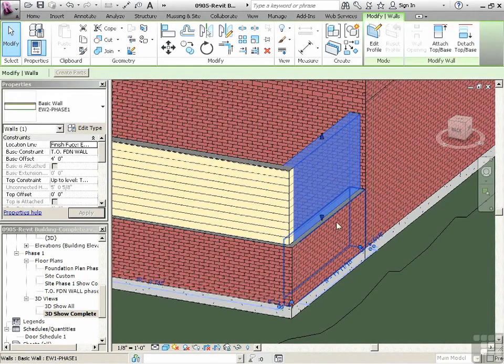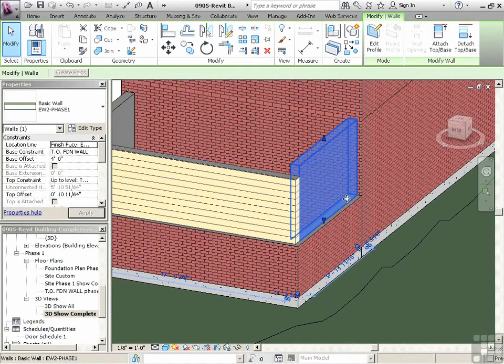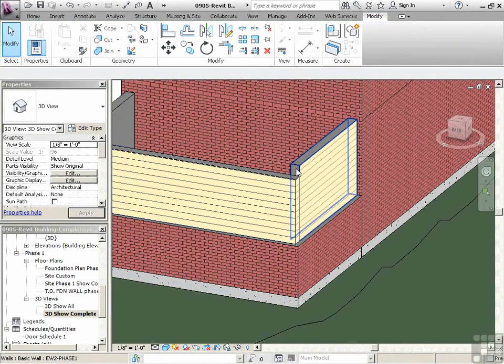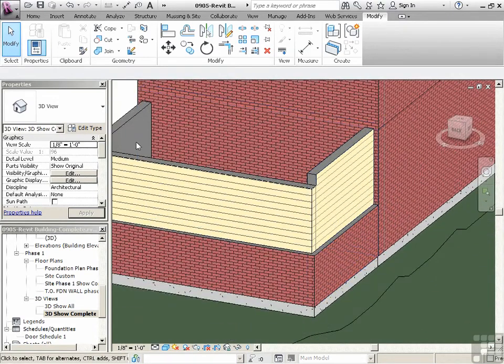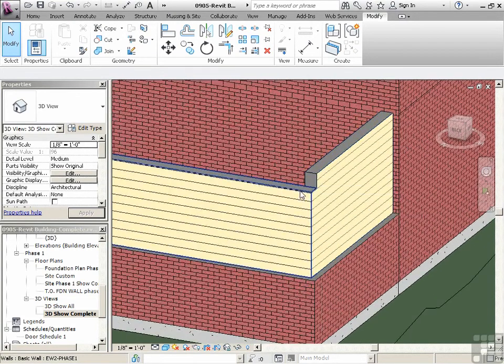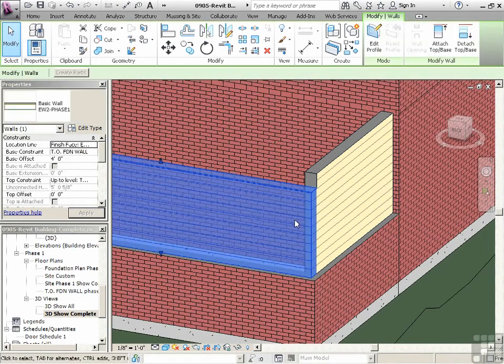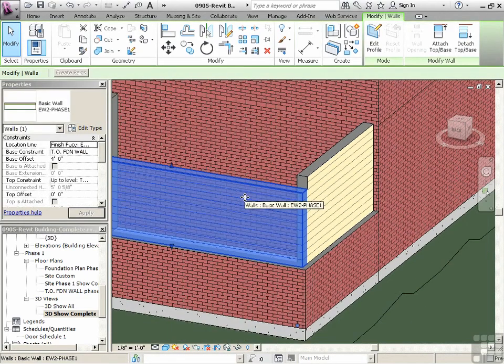Let me click on this wall. Notice what happens? When I drag that up, that wall goes up and then this entire wall right to the edge stays down at its level. So this is something that you have to work with sometimes. Sometimes you're working on roofs, gable ends, and there'll be a little empty triangle where the roof is. And you'll just want to make sure that the gable wall takes precedence as you raise that up.